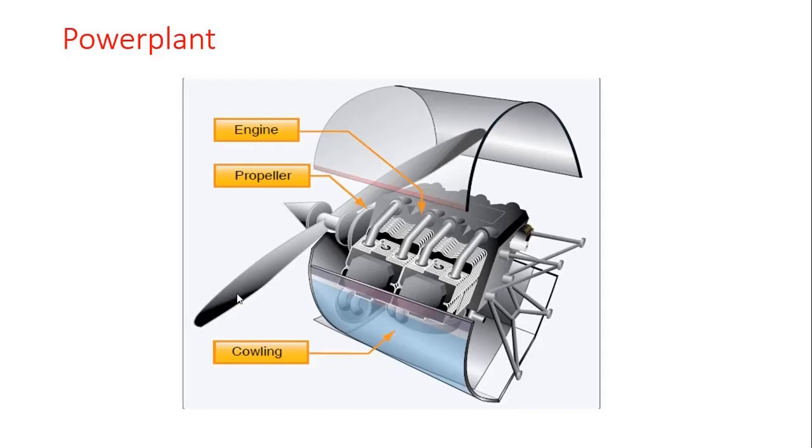There are significant factors involved in the design of a propeller that impact its effectiveness. One is the angle of propeller blade, which is measured against the hub of the propeller, keeps the angle of attack relatively constant along the span of the propeller blade, reducing or eliminating the possibility of a stall.